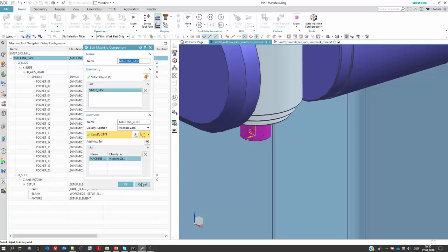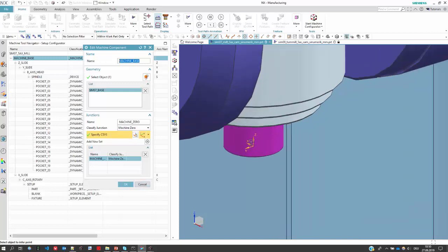And for sure the rotary axis now, depending on the setting what you did here in the machine 0 position, which means the positive A-axis direction is clockwise around X. The positive Z-axis direction for the rotary is now counterclockwise around the Z, and the same here for the Y-axis.